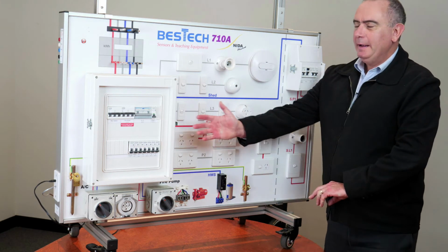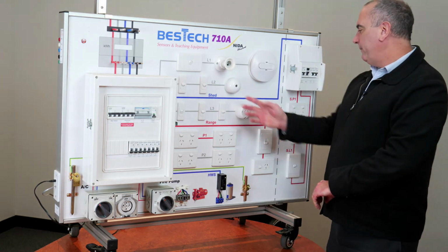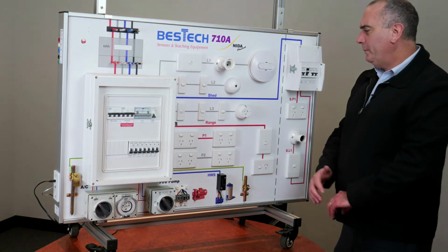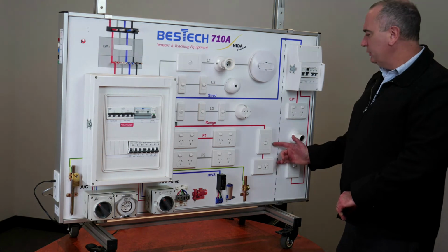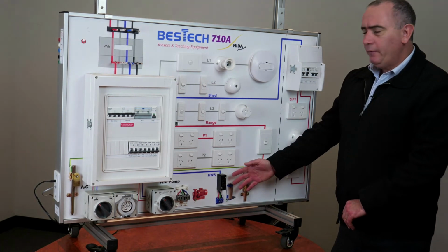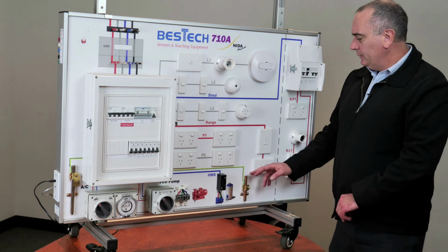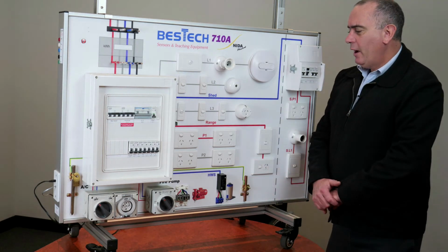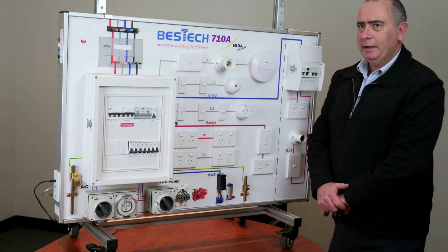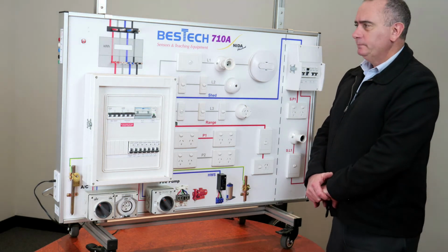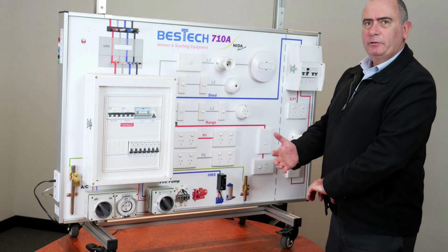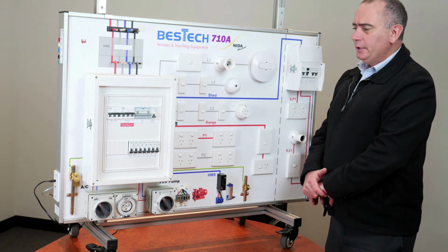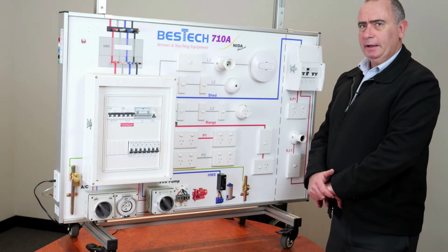As you can see, we've got a main distribution panel. We've got 4 lighting circuits with different lighting fittings. We've got 2 power circuits, a range, a hot water service with an isolation switch, an equipotential bond, a safety circuit, which is a fire pump, and an AC 3-phase connection. We've got the ability to put extra low voltage 3-phase on the left-hand side there, so we can do a phase rotation test along with a connect-disconnect.